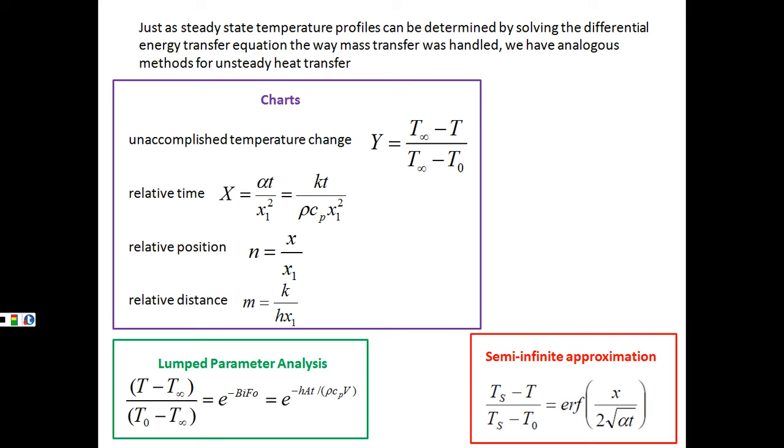And they also said something that I think is worth noting here, that the surface has zero thickness. And so this surface itself is not storing any energy, and the heat reaching the surface of a body by convection must continue its journey within the body by conduction. So once it reaches there, it's not like it's going to stop and everyone's going to hang out on the beach, right? They've got to continue their journey inward. And that surface itself is not a place where that heat is going to be stored. It's just the interface between the modes of transfer, or transport that are occurring.